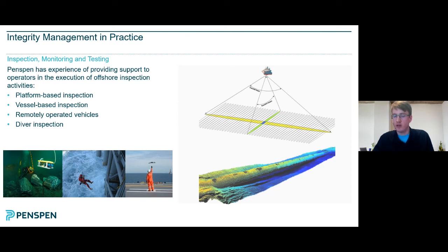So offshore, there's some challenges in terms of even conducting visual inspections. I think traditionally rope access teams were required to inspect things like risers and riser clamps. What we're finding is that increasingly drone surveys, or unmanned aerial vehicles as they're called, are being used, and that allows for more rapid visual inspection to be conducted. There's obviously a lot lower risk. Potentially it can be launched in worse weather conditions as well. And what that allows you to do is carry out a sort of visual inspection, and then if that inspection determines that there's a requirement for further inspection, that can be when you use your rope access team to either conduct some kind of non-destructive examination or carry out fabric maintenance or some other type of repair.